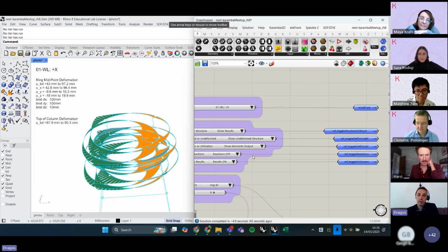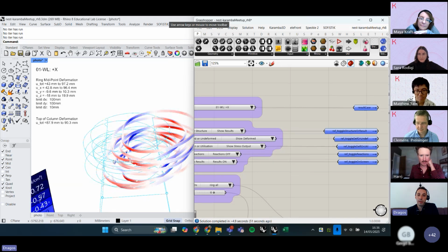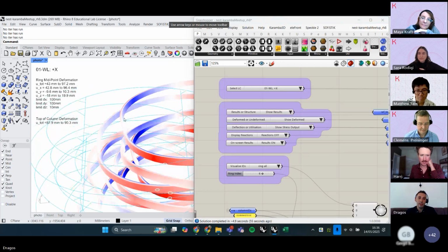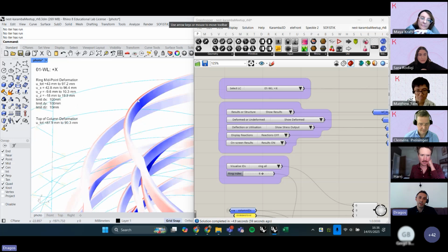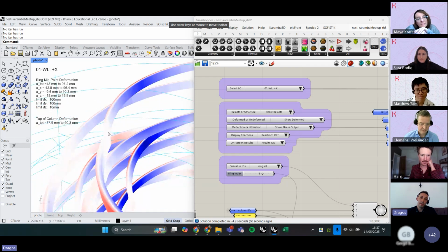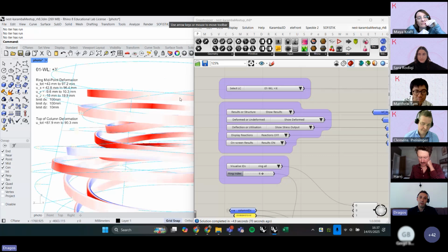And yes, one more thing I wanted to show. If I look at the stress input and I look at the rings, you can clearly see the middle axis, which is aligned to the axis of the element. So the ring is bending in its own plane. This is the splice release. There's no moment transferred that way, but there is moment transferred along the ring.